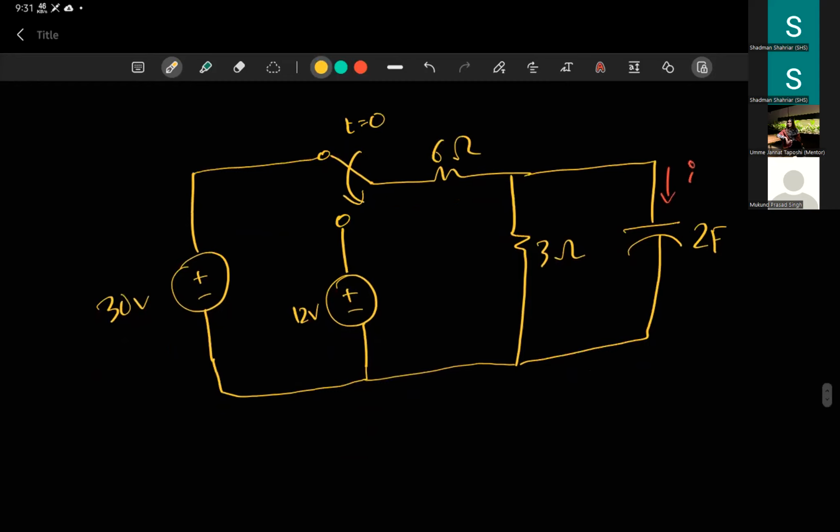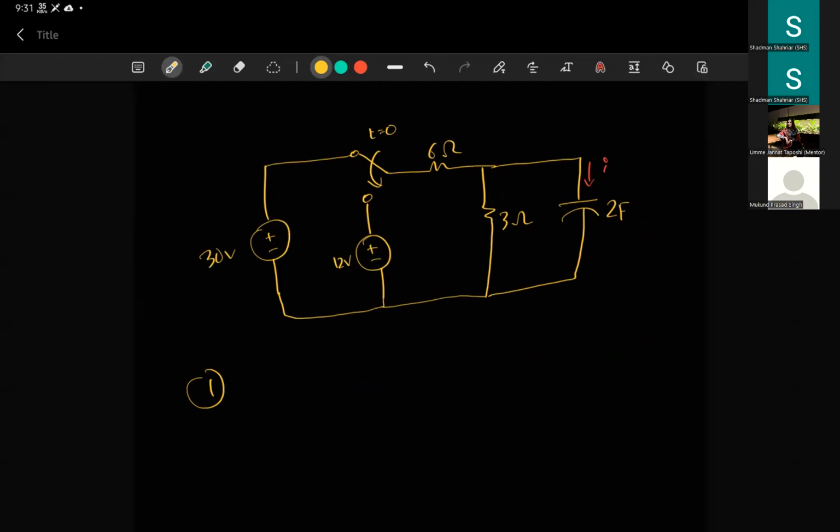Okay, okay sir. One situation, first of all, you have a capacitor here, right? Should you write the equation for voltage or current? So you focus on voltage. The question has asked you for current, but still what you should try to do is find this voltage.